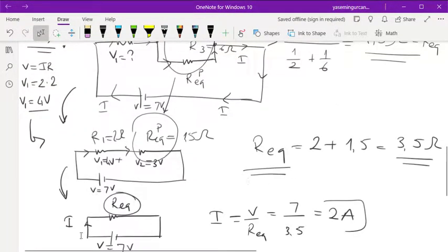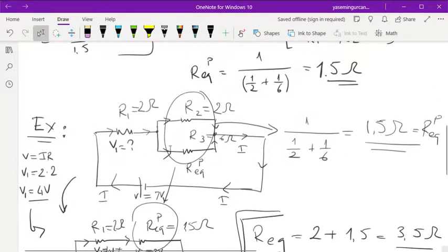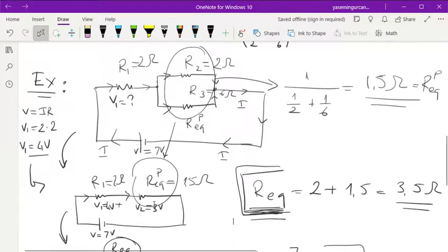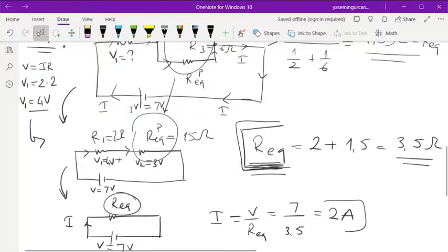And then by using, so again, step 1 is to find the total resistance value. R equivalent of the whole circuit is what you need to find first, okay? And you do that basically by adding parallel components first, getting rid of it, redrawing it simply, and then getting rid of the series parts, and then writing the total circuit as having one single resistor, which is the R equivalent of the whole circuit, and then using that R equivalent value for total current on the main branch.